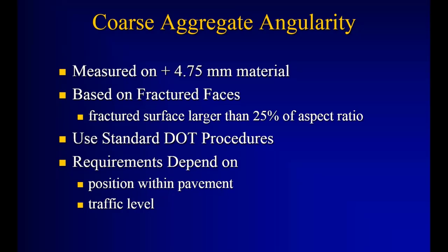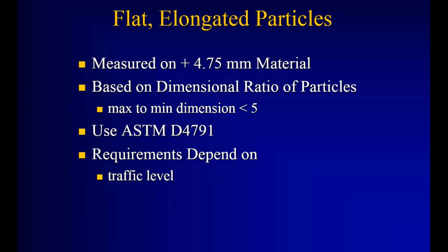Again, in the Superpave system, as you went up closer to where the wheels hit the road, you had higher and higher fracture requirements. That fracture, that angularity gives us strength, internal or cohesive strength in that mix, in that aggregate blend. And the higher the traffic section, the more trucks basically, the more fracture you need.